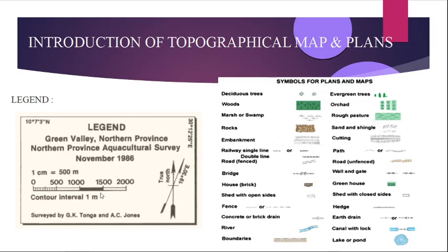The method of topographic survey should be selected considering the scale. For example, the purpose of the survey will be served if the average error in measurement of distance is 1 meter for a scale of 1:4000, because a surveyor can plot the distances to the nearest of 0.25 mm.